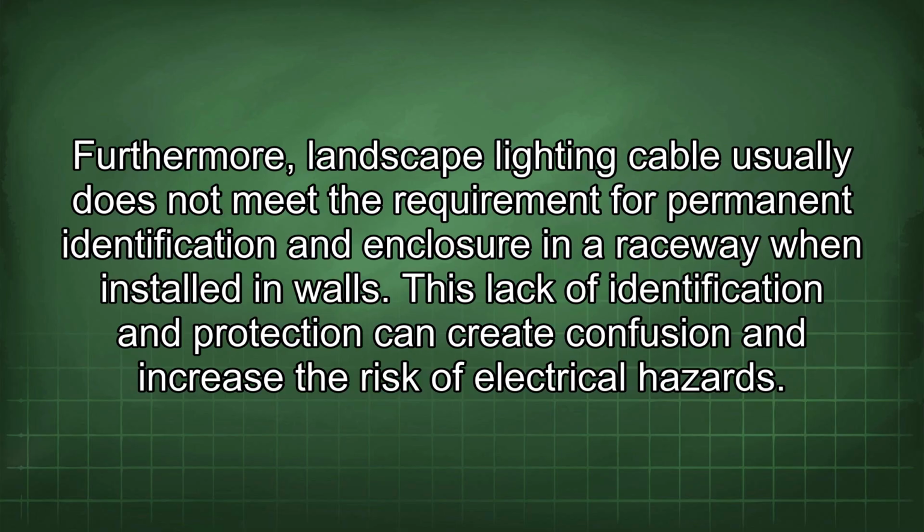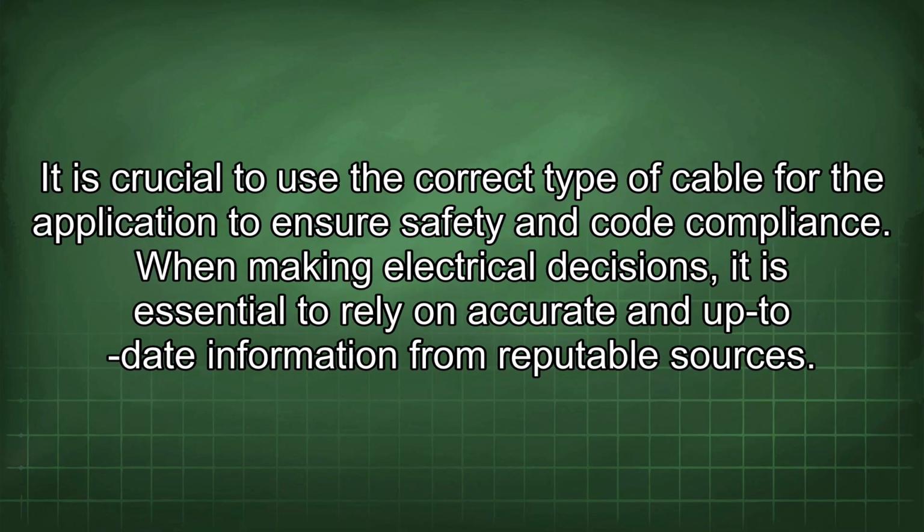Furthermore, landscape lighting cable usually does not meet the requirement for permanent identification and enclosure in a raceway when installed in walls. This lack of identification and protection can create confusion and increase the risk of electrical hazards. It is crucial to use the correct type of cable for the application to ensure safety and code compliance.